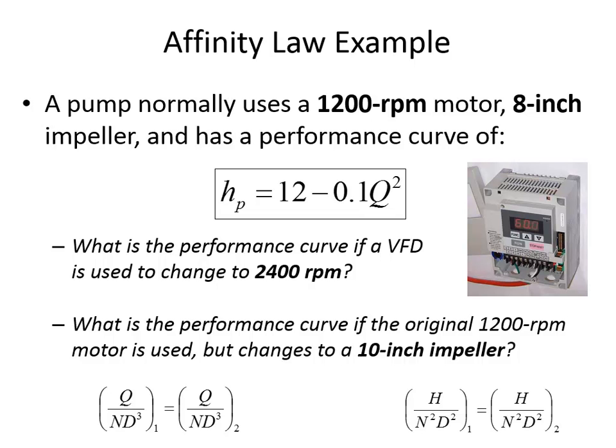And I think the reason we're doing that, you'll notice that diameter is one of the terms, but in the description of the problem, it doesn't say anything about changing the diameter. It's the same pump from case 1 to case 2, so the diameter hasn't changed. So D1 equals D2, so we're going to be omitting it. D1 equals D2 is what you do when it's the same pump just being used under different conditions. So we can rearrange that and express Q1 in terms of Q2.